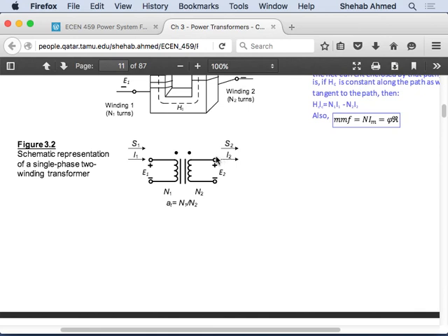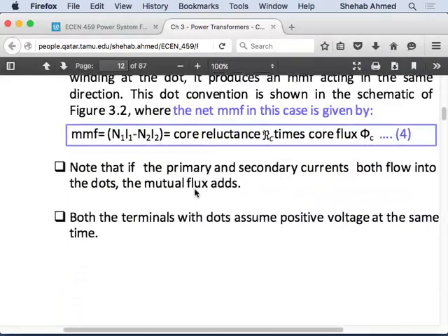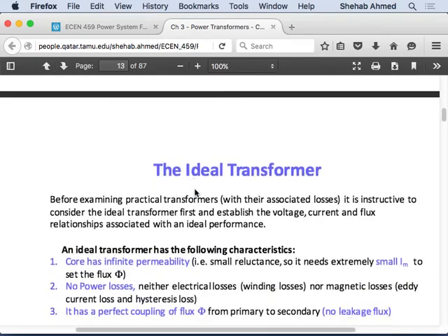With that assumption, we have this voltage polarity. If I put the dot on the other side, I will flip the voltage polarity. We will want to use that when we play with the phase shift stuff that I told you about. Vector groups, we want to develop different vector groups, we will play with where we place the dots on the cores. So we will spend some time on that.